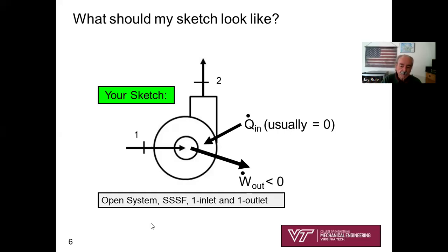Of course, my model, what's my thermodynamic model? Open system, steady state, steady flow. So the inflow exactly equals the outflow. This pump is not getting fatter or skinnier. It's just operating steadily, okay? Obviously one inlet and one outlet.